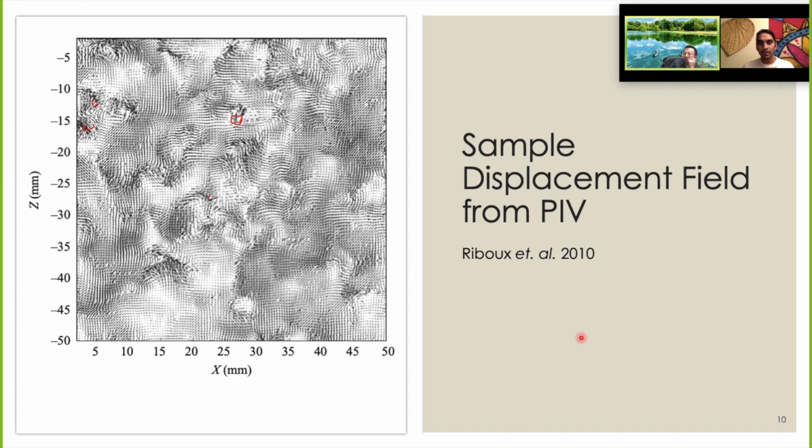So if you blow this region up, you will see a very strange velocity field. That's not because the flow is like that. It's because there's a bubble, okay. The valid way should be, at least, you should kick out those bubbles before you process the PIV images. But that takes a lot of time, and also it's not a trivial job.